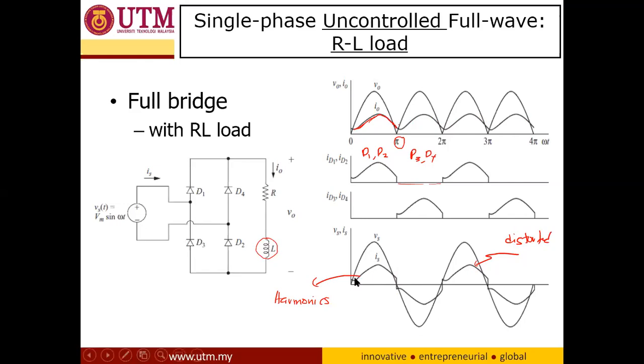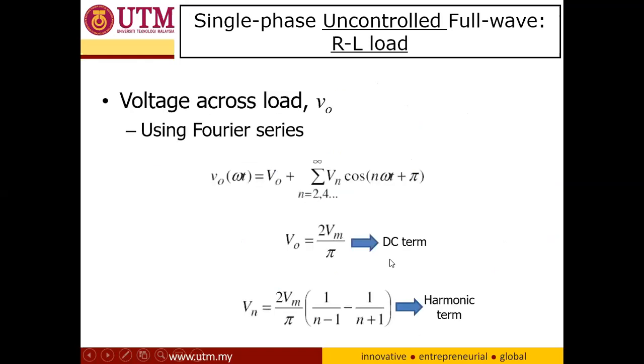Even though the current is in phase with the voltage, please note that the power factor is measured based on a sinusoidal voltage and a sinusoidal current, but this one is no longer a sinusoidal current.